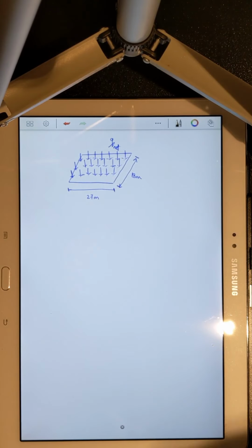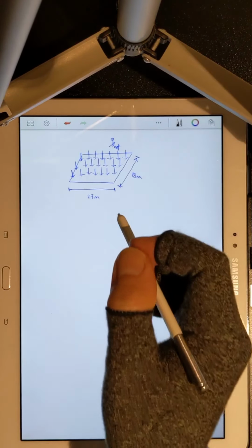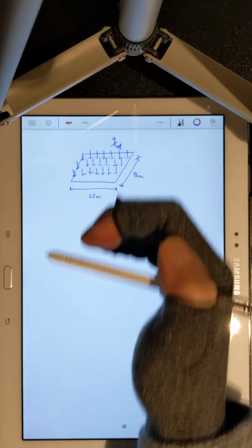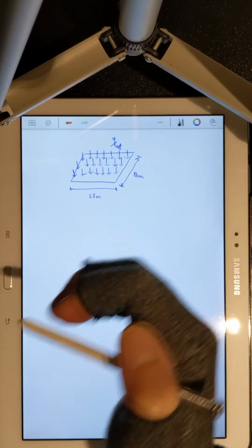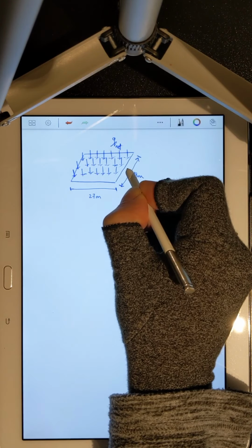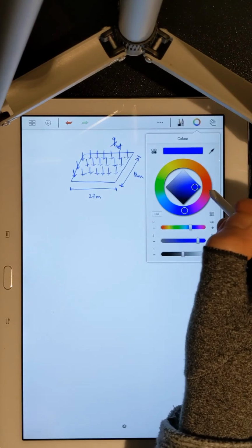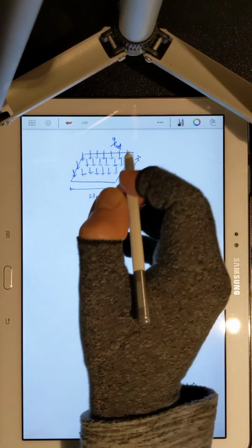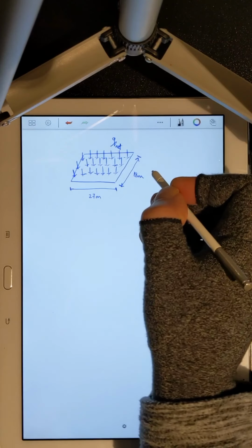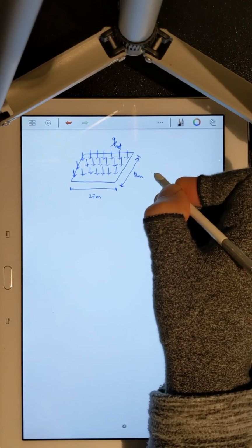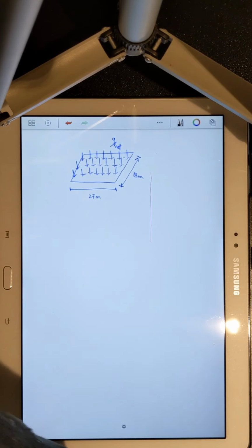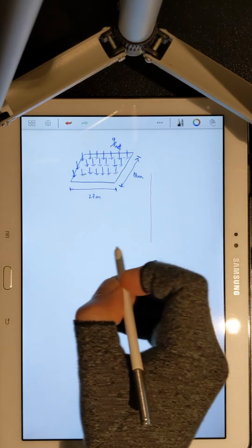And you have a number of sub-layers, and you do need to calculate the effect of this net stress, or how much of this net stress remains at the center of each of those sub-layers. So you have basically a distance from the bed of the foundation to the center of each sublayer.